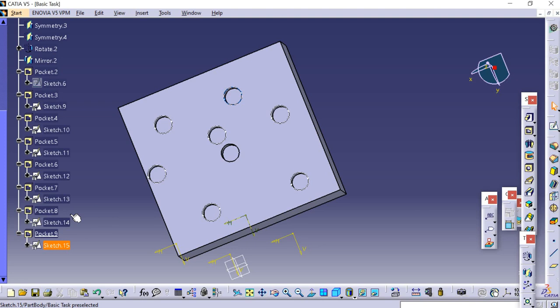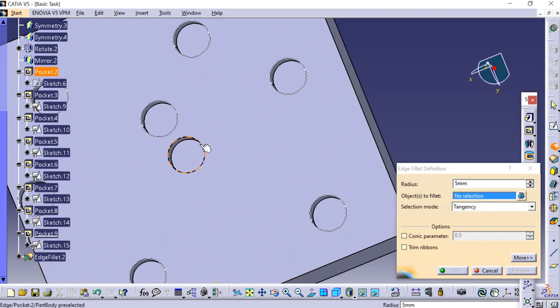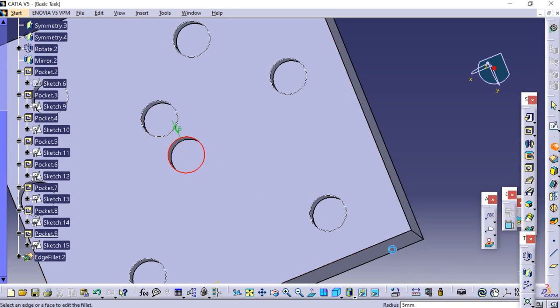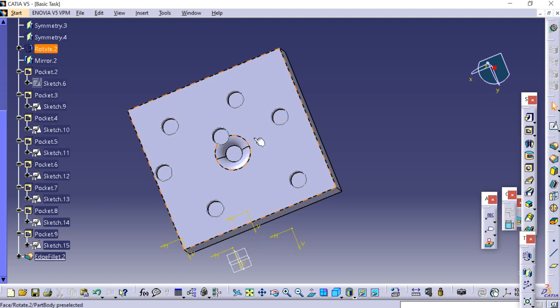During our designs, we may decide to perform specific operations in certain number of instances. So if we want to fillet it here, we can do it separately, like that. Or else everything will get filleted at the same time. So we use exploding patterns.